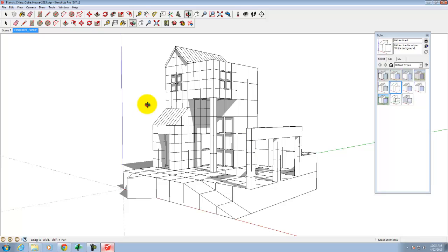Once you have the view established the way you want it, I'm going to flip over to tutorial 4.5 in that you want to be able to save this view so that you can come back to it over and over again. And when you start to do lots of exports, if you accidentally hit the orbit command or the pan command and then your exports don't line up anymore when you're dropping them into Photoshop, you just want to be able to go back to whatever that is. Kind of like those of you that have taken Rhino, when I tell you to save your view in Rhino before you start renders, because you can go back and make modifications and come back to that view.